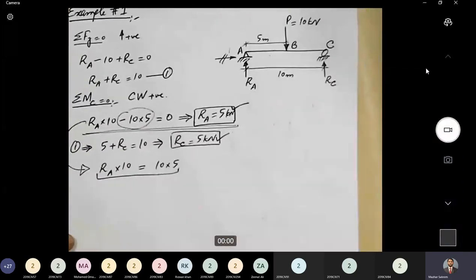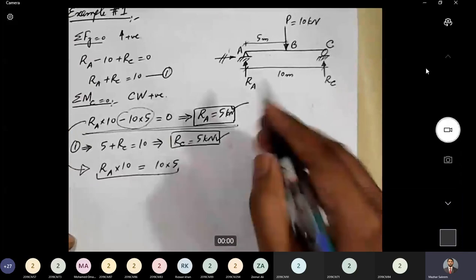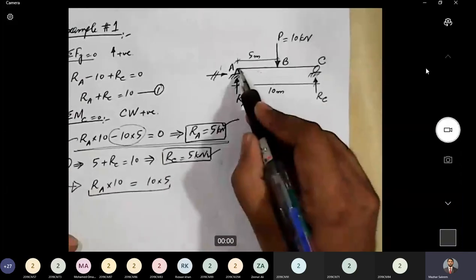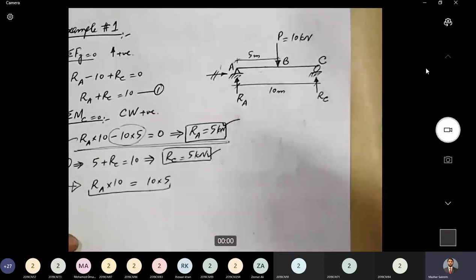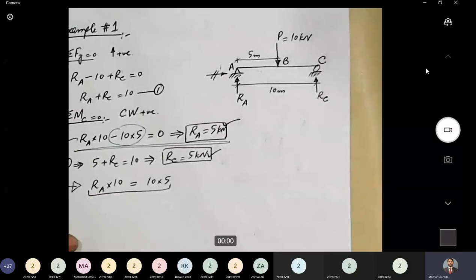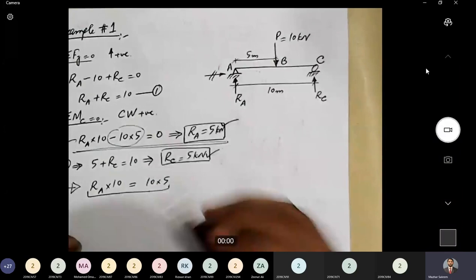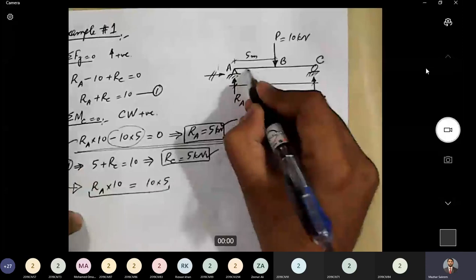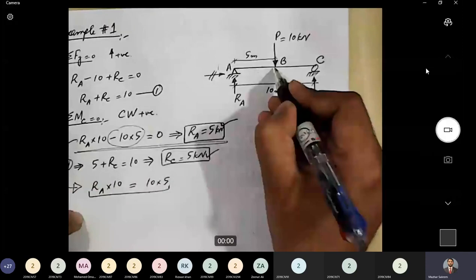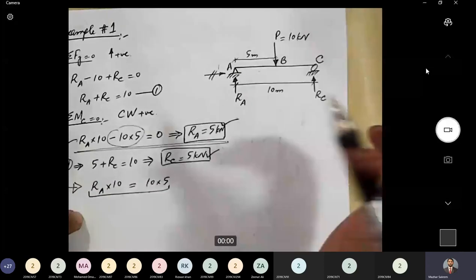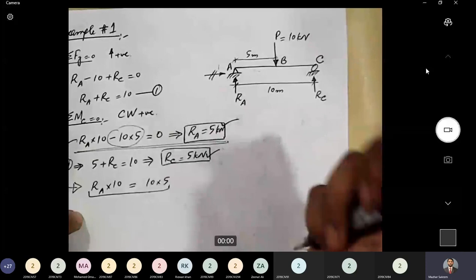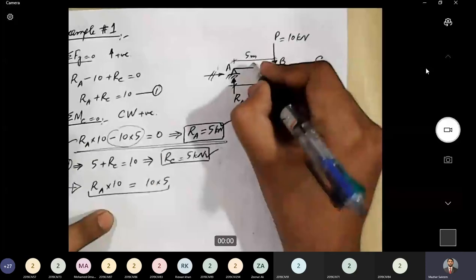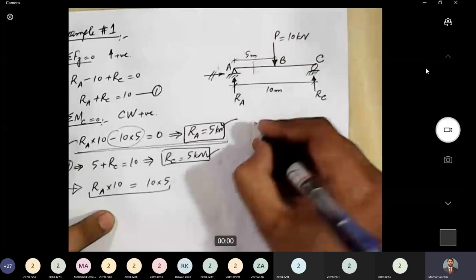Now, how will we do that? For that purpose, we need to identify where there is a change in applied loading or support conditions. So wherever we see a change, we define a new portion. So let's start from point A. As we move in this direction, what is the location where we see the first change? It's at point B. So it means that from point A to point B, we have constant loading and end conditions. So we will define one portion as portion AB,